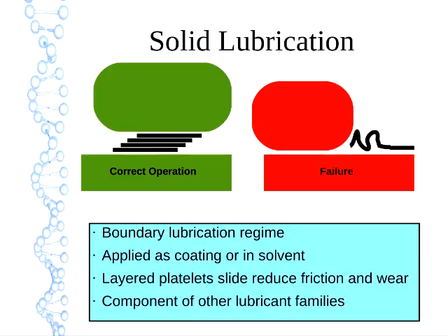And this is also a component of other lubricant families. You put these solid lubricants in other lubricants. So what you want to do here is you want these solid lubricants to be kind of sliding, the different layers to be sliding, and you have a kind of a light film of them separating the surfaces. But sometimes they will peel up from the surface, kind of delaminate, debond, push out of the way. And then you've got the direct surfaces coming into contact, and that is not what we want.